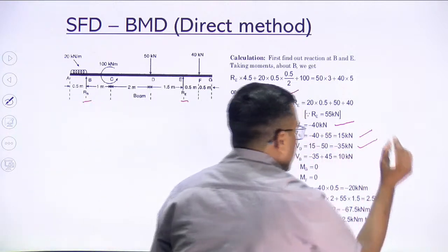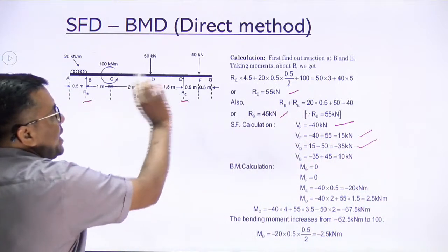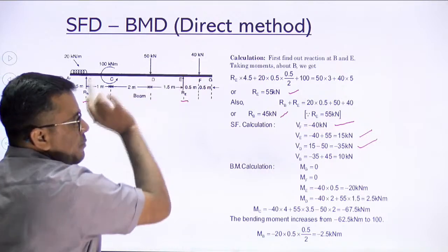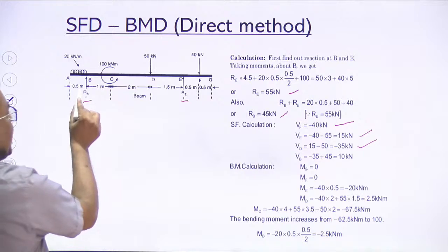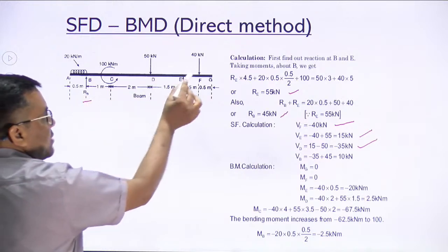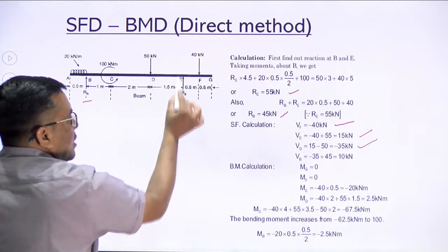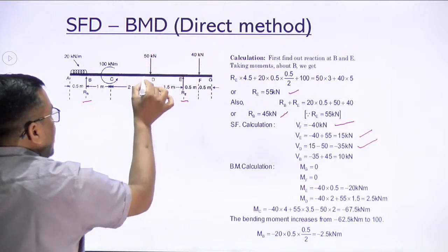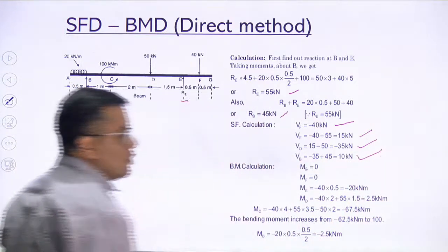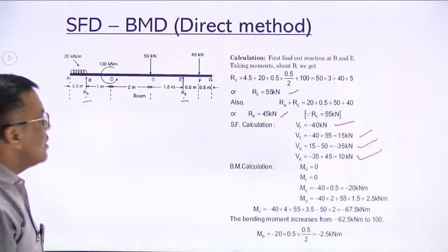Calculation at D, and D के right side में whatever the forces are there, all the forces, algebraic sum of all the forces. Then at point B, shear force will be the forces on the right side minus 40 plus RE minus 50 plus RB. It is coming out plus 10. Okay.